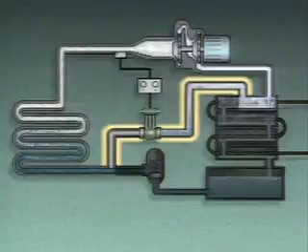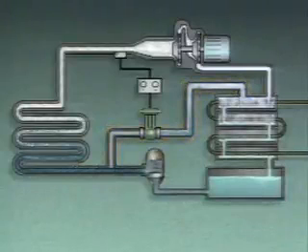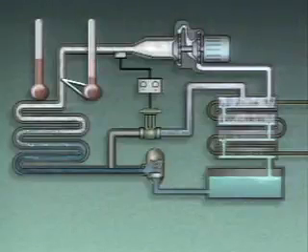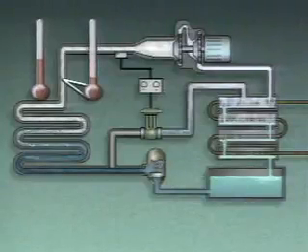When this is done, the refrigerant that flows into the evaporator is warmer. The flow of refrigerant through the bypass line is controlled by a control valve to maintain the temperature around the evaporator. If the temperature around the evaporator gets too low, the temperature of the refrigerant flowing to the compressor will drop. When that happens, a temperature sensor sends a signal to a controller, which in turn sends a signal to the bypass line control valve, causing it to open slightly.